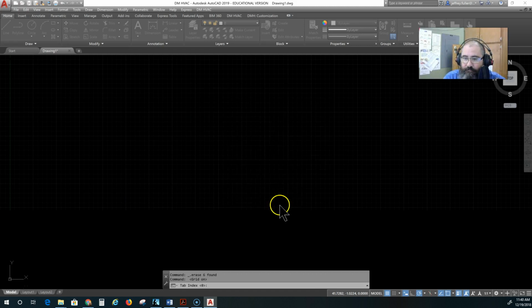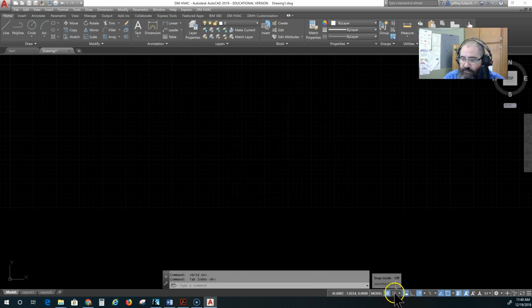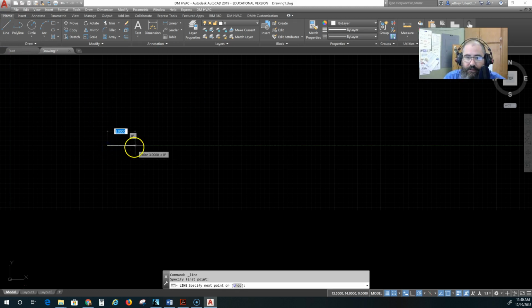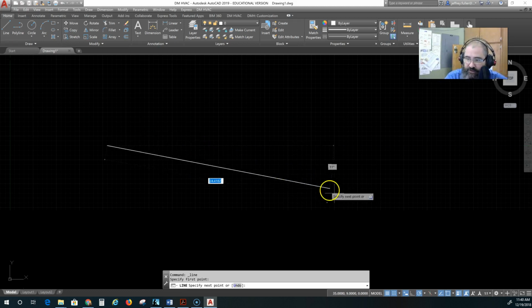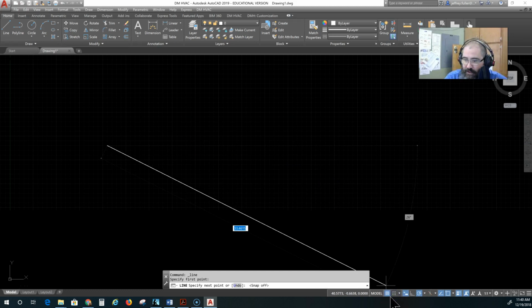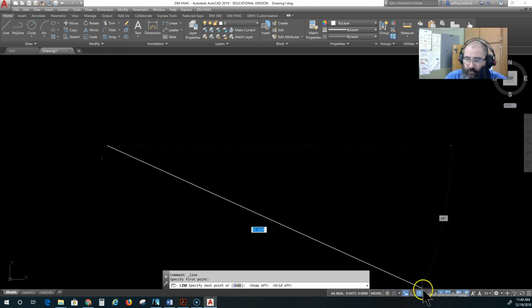I'm going to click OK, and I'm going to turn my snaps on, and it's real easy to see how this works. I'm going to start a line, and as you see, as I pull the line to the right, it does snap every half unit, and it just locks into that position to help you draw more accurately. Okay, that's pretty much the gist of the grid snapping. So let's turn grid snapping off and grids off and go over to our next one.